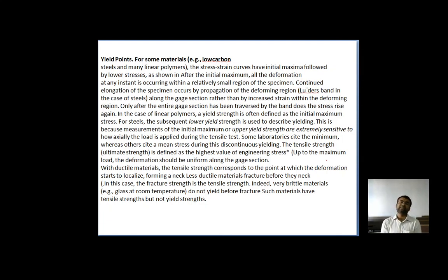So this material is cut from that complicated part after processing and is to be made into test specimens. They have been subjected to the same processing steps as the bulk of that particular part. In practice, these specimens may not exactly match the bulk of the part in certain important details, such as the grain pattern, which is a critical area of casting, which I told you.